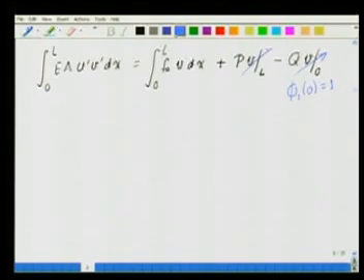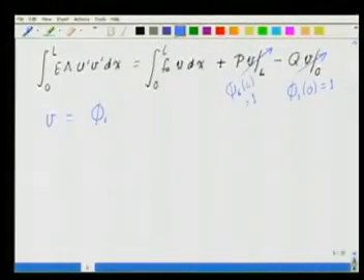V at L, which of the phis is non-zero at the point x equal to L? This is phi 6 at L, this is equal to 1. So, from this what do we see? That if I look at the equations, put v equal to phi i, then this P has to contribute to the load vector term corresponding to phi 6, and Q has to contribute to the load vector corresponding to phi 1.